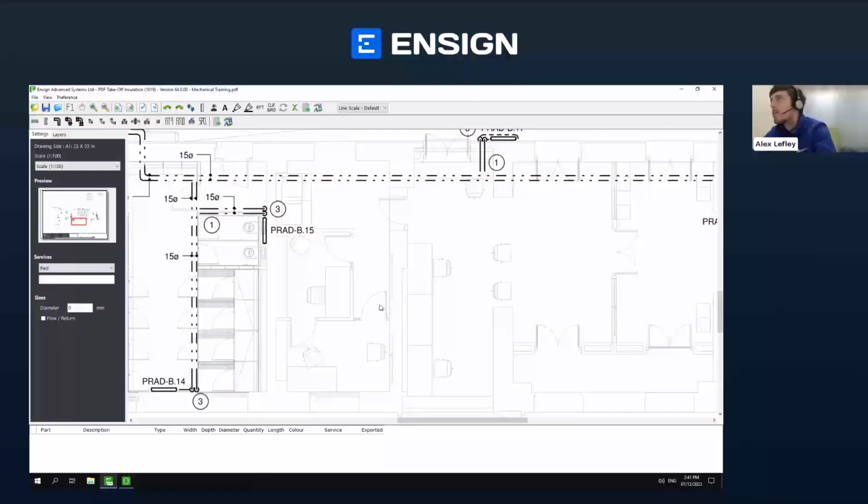We'll use this one. So I want my ruler tool. The ruler tool is a nice, easily distinguishable one. It's one that looks like a ruler, and if you hover over it, it says measure distance. So just give that a left click, and then you should find that your mouse is now this sort of black crosshair icon, and the ruler is now highlighted up there at the top to show you are using this function. Then just measure your known distance by left clicking at one side, left clicking at the other, and that's now giving me the distance of about 850 mil, which I know is about right for a doorway. As long as it's not extremely wrong, then you know that you are going to be correct.